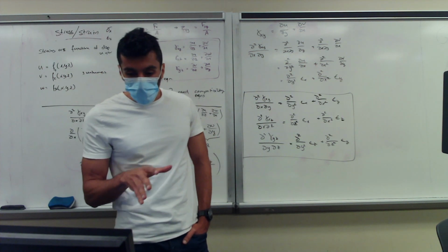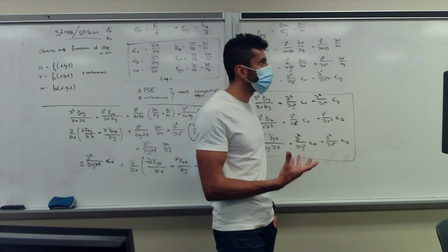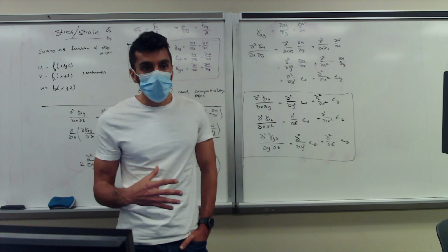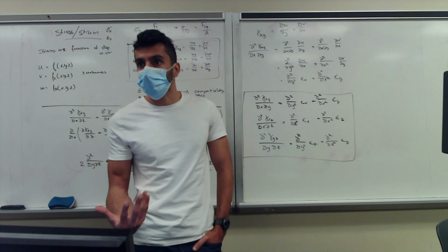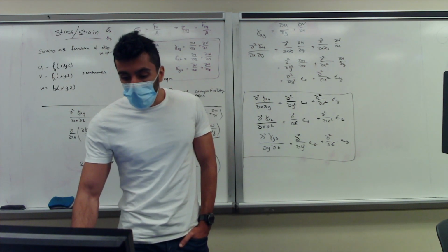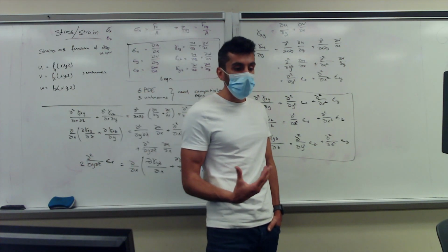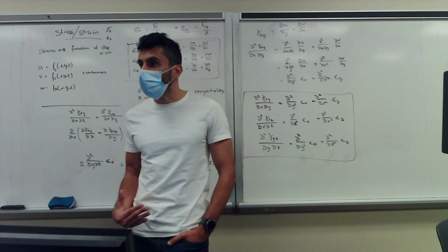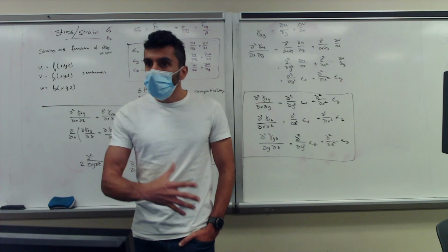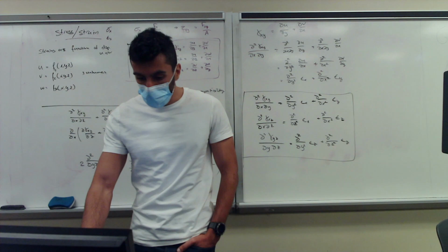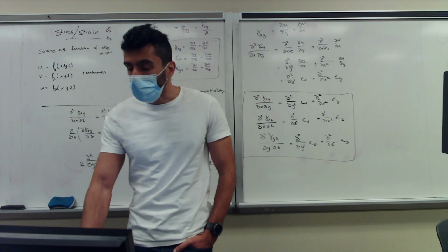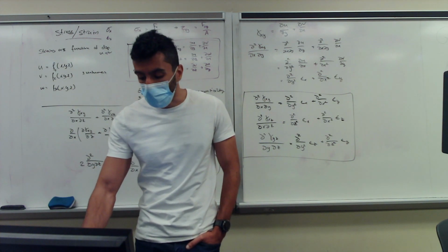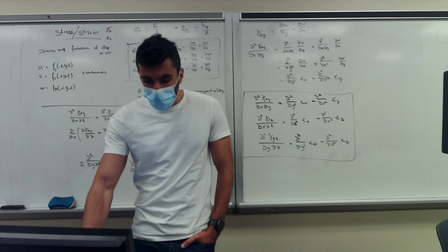So like I said, we start off with taking forces and looking at how failure occurred, and for that we take an arbitrary shape, put a force on it, and notice that the forces are also internal forces. Then if we want something that is geometrically independent, we normalize with respect to the area, which yields an intensity that we call stresses. And of course, taking the stress in direction x gives you sigma. The force in direction x gives you stress in direction x, and xy, and so on. So that's the first couple of slides.